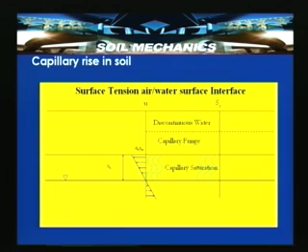Capillary saturation, which is in contact with the water table, can have complete saturation. What we discussed is that minus Hc gamma W is the water pressure, that is the negative pore water pressure or suction pressure. Hc is the capillary rise above the groundwater table, and below the water table again there is positive hydrostatic pressure.